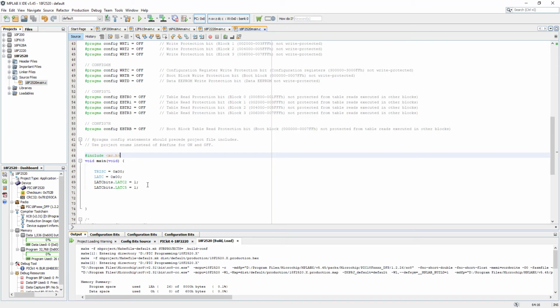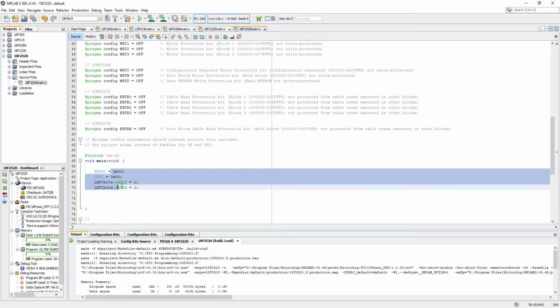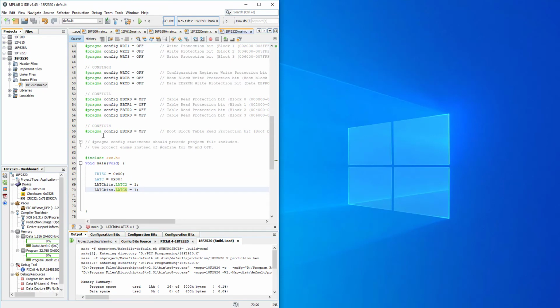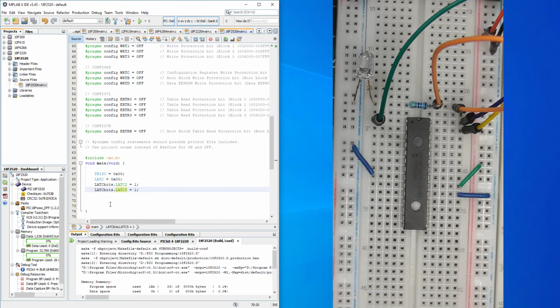As we said before, a program written for any PIC18F series will most likely be okay for the next PIC, but there is a major difference in a PIC's memory, which we're going to talk about later on for the program memory. But small programs, you can use them for any 18F series PICs. So okay, let's go ahead to our PIC board and let's change the device.